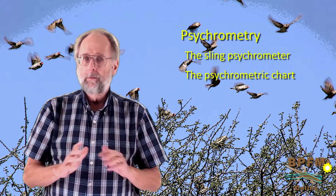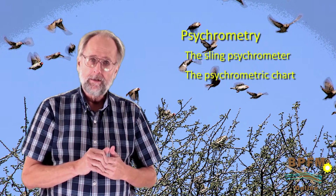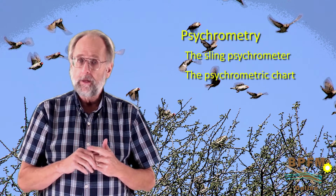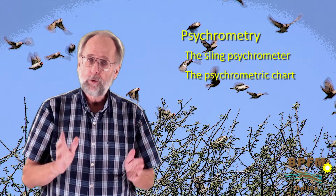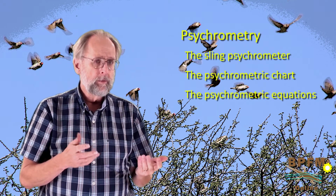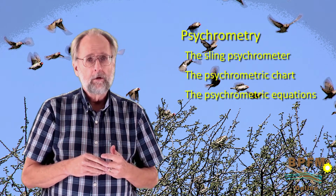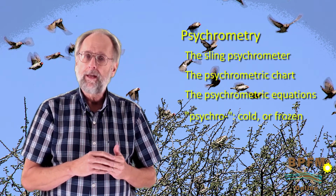Before we go on, just a word about terminology. The prefix psychro is usually used today as a synonym for moisture in the air. We use a psychrometer to measure humidity, or we convert between the various measures of humidity using a psychrometric chart. All these things are derived from a suite of equations known as the psychrometric equations, which don't really describe humidity, but actually describe the energetics of the change of state of liquid water to vapor. The prefix psychro is actually derived from the Greek word meaning cold or frozen.